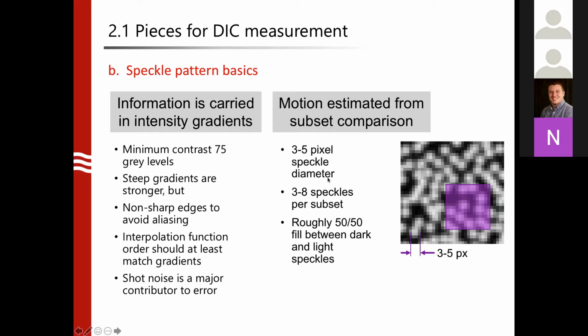Also, some people may ask, can I just use larger speckle dots? You can, but you may lose some spatial resolution afterwards, so just pay attention to that. Basically, for all these dot sizes, for this length scale, you need to satisfy the Shannon sampling frequency. So it means you should have some estimate of your deformation characteristic length, and then you can define the typical dot size for your patterns.